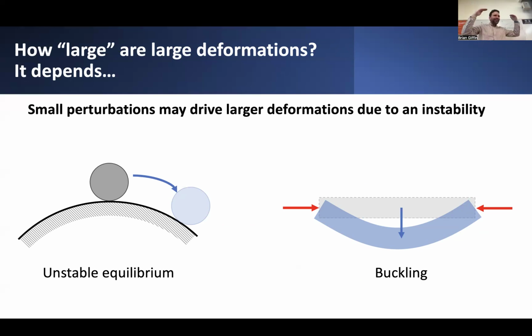So a very, very large axial load with a very small delta can result in a further increase in internal moment, which further drives more transverse deflection, and it's this reinforcing cycle. So that phenomenon is likely what you're familiar with as buckling. It's the behavior of an instability that's driven primarily due to a geometric nonlinear effect.